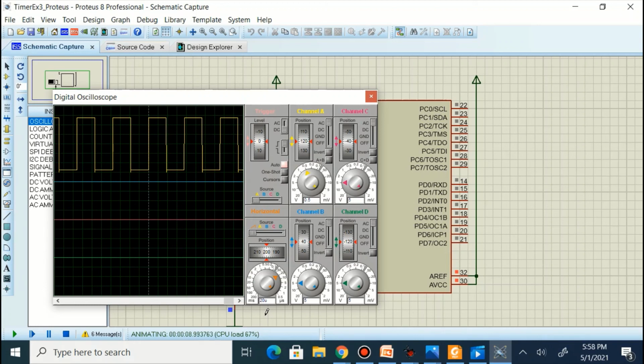So we can approximately find it as around 70 microseconds, and the square wave observed in the digital oscilloscope is also around that, because a little less than 4 slots of time period is being utilized over here.